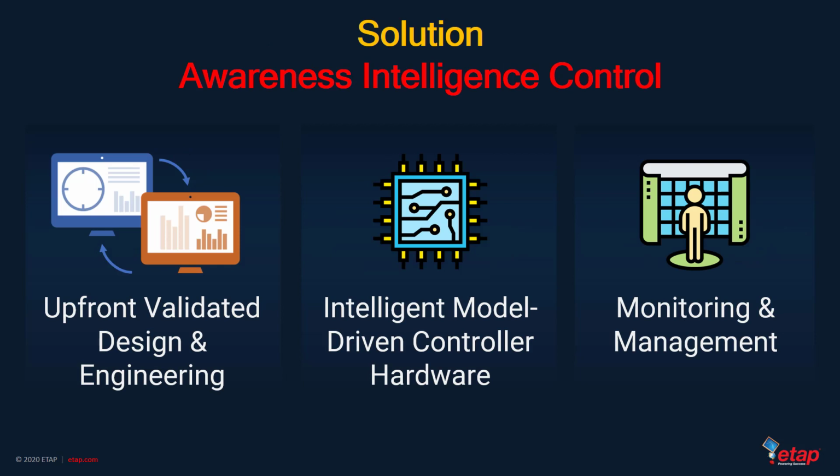The key is therefore to use a digital control twin of the actual power plant controller and the power system model together with time series analysis and forecasting to guarantee its performance under various grid and plant operating conditions. Therefore, an integrated solution with a situationally intelligent power plant controller is the key to maximizing yields and meeting TSO or transmission system operator stability and power quality requirements at the point of interconnection.